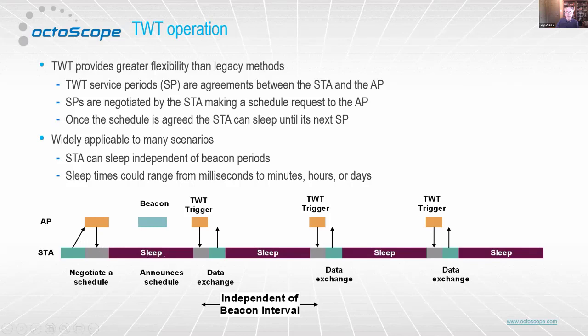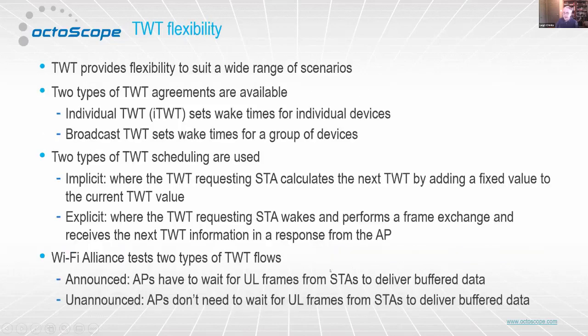There'll be sleeping going on. There's a beacon happening, but nobody cares. And then there'll be a service period where the device will wake up, then it'll send and receive some data. It'll go back to sleep. It'll keep doing that over and over again. And as you can see, there's no beacon even going on in here. I mean, beacons are happening, but it's not relevant to TWT.